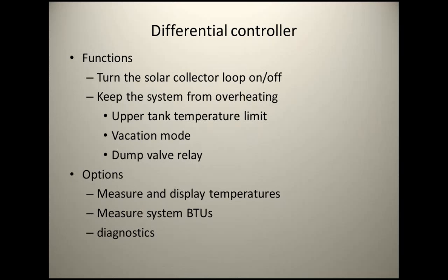elevated my pressure in mine to 50 pounds of pressure, and my glycol loop could stay static at 338 degrees before I produced steam. So I could hit almost a 100-degree day before I ever ran into the problem of overheating. And if I did overheat, all I did is ran it out, and it ran the loops through the ground. It kept the frost off the ground, and all my stuff started to grow earlier in the spring, and I could grow later in the year before I had to harvest certain things.